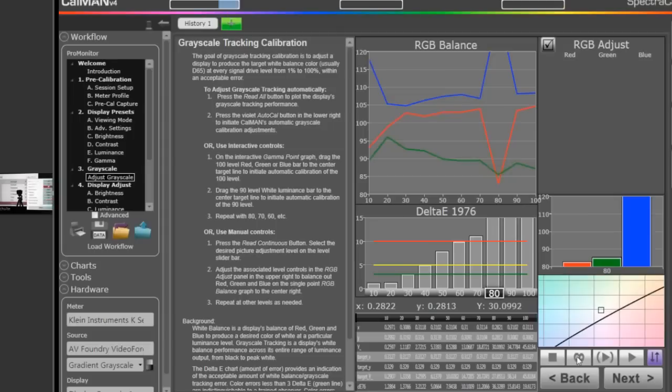And we get down to red, green, and blue contrast controls. Contrast controls are another name that LG has for the high brightness white balance controls. As we go down farther, you'll see that we have red, green, and blue brightness controls. Those are what other manufacturers might call offset controls, or cutoff controls. They are the low brightness color balance adjustments.